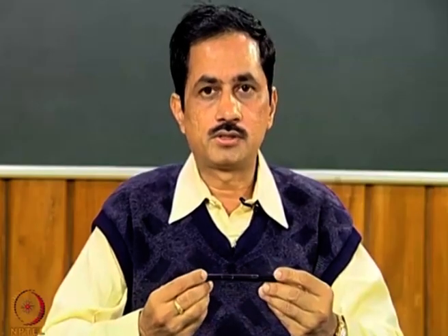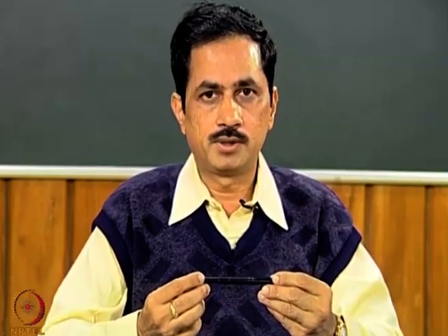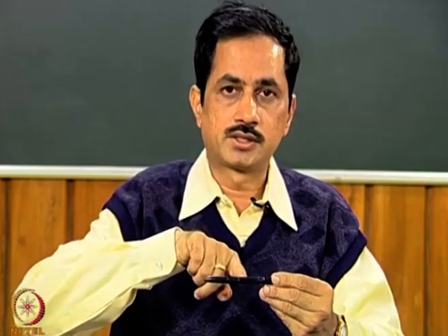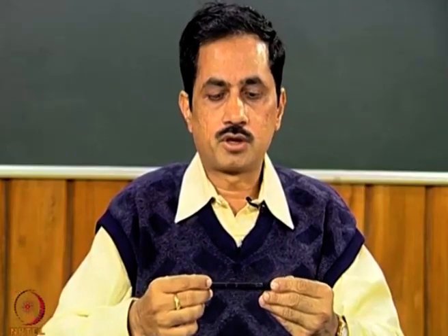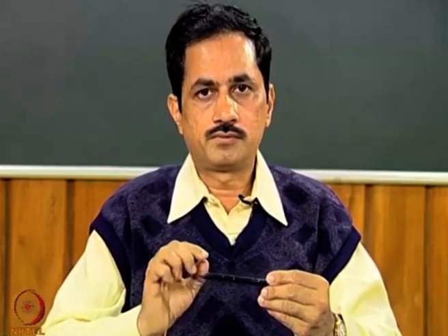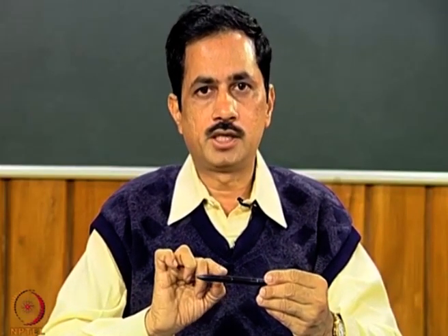So, this particular stiffness K_uv I have defined, in which we are taking the force direction u, the change in the force in u, and the displacement in the v direction. So, this is a cross coupled term. In this particular case, if we are considering a rotor which is supported on such a hydrodynamic bearing, if you are giving a force in the u direction, that is the horizontal direction, there will be displacement in the vertical direction also.